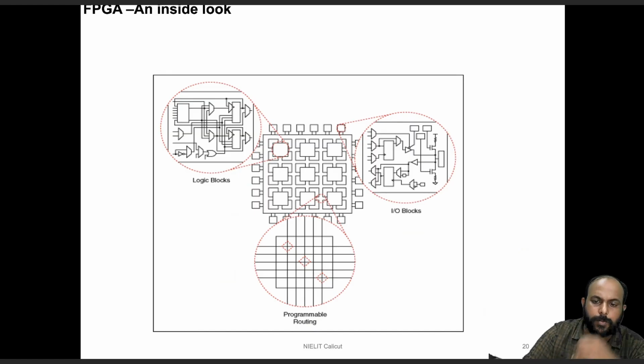So inside an FPGA, mostly FPGAs carry three building blocks. It has these boxes called logic blocks, which basically consist of reconfigurable logic. Depending upon what design you are putting in, your design may be consuming multiple logic blocks. The design will be partitioned, and each logical block will be put on a logic block, which is shown there, often called a configurable logic block in FPGA terminology.